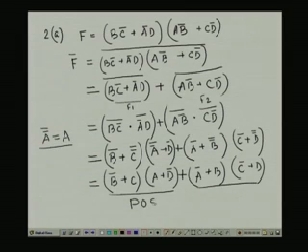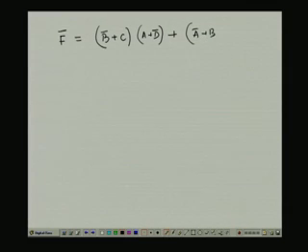This is one POS, this is also one POS, but this one plus exists here. So, this is not any standard form. If I want to make this a standard form, then we have to simplify it further. So F complement becomes (B bar plus C)(A plus D bar) plus (A bar plus B)(C bar plus D).